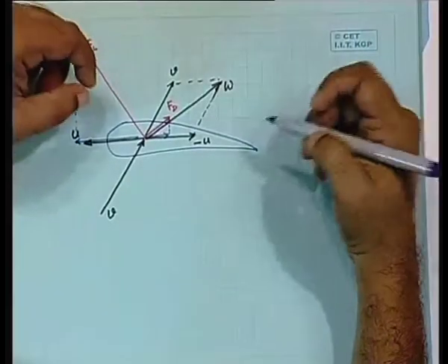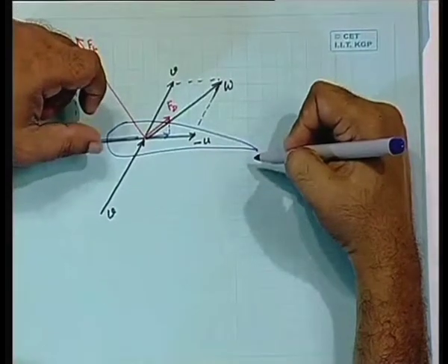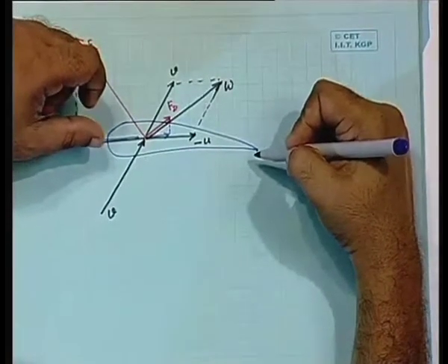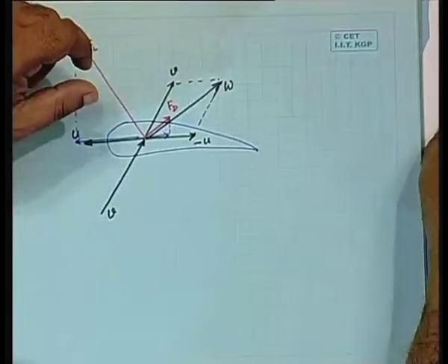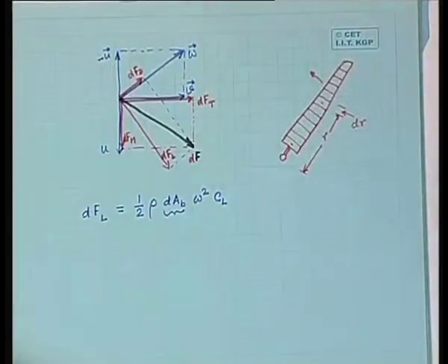What actually happens is that people have experimented with various designs. The experiment is normally carried out in wind tunnels. They have constructed large wind tunnels in which this particular shape of the airfoil is put, wind is blown, and they make accurate measurements on the amount of drag produced and amount of lift produced, and from there this lift coefficient and drag coefficient can be calculated.